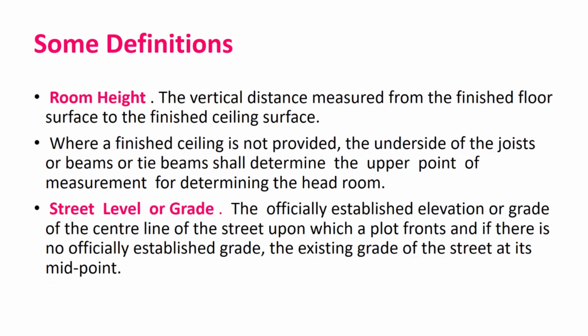So, I'll just say for shallow foundation what they are saying, pile foundation in soil, well foundation in soil, penetration into the rock, embankment details, a lot of things they have given. I'll see one of the cases, shallow foundations, normally other than rock, the depth of investigation shall be up to 2 to 3 times the estimated width of the largest foundation below the expected founding level.